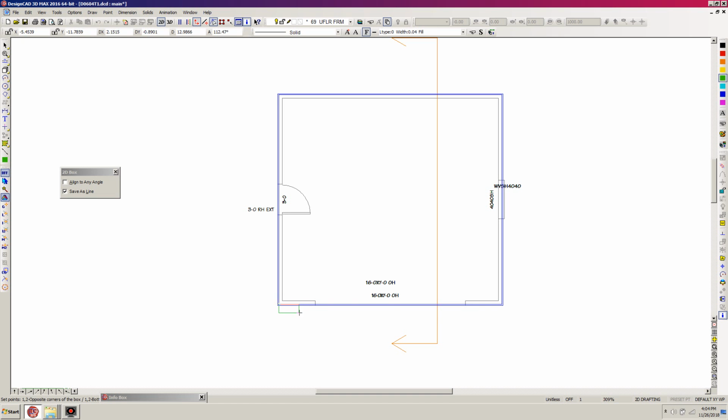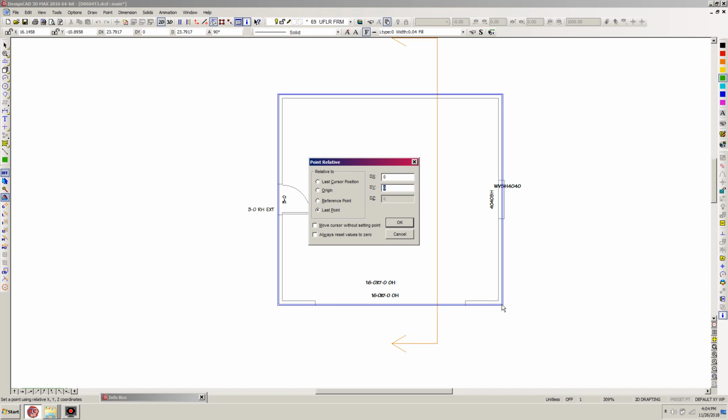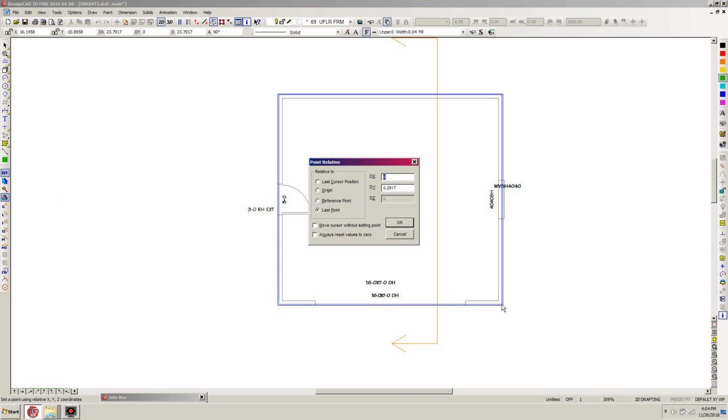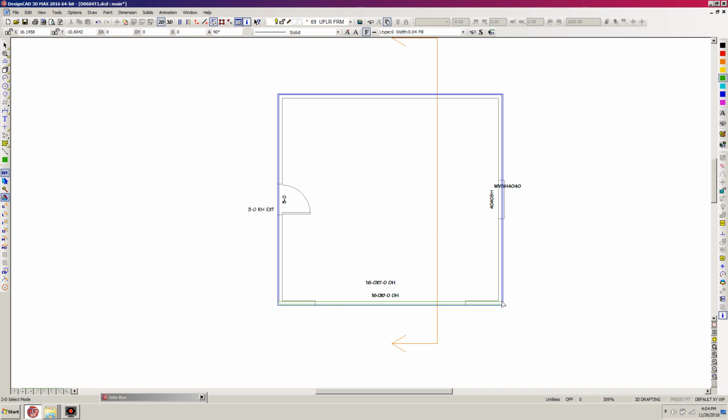Right click here, and then I'm going to gravity move here. Oh, I need to hit H to go out of orthogonal mode. I'm going to gravity move here using the comma, and then go up on the y-axis 3.5 inches. Oop, that didn't work. Try it again. Right click, gravity move. The reason it didn't work is because it was taken from the last point, one of those things I often forget. Hit enter. Okay, so we have one joist already set up here.